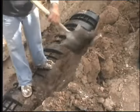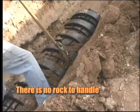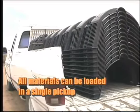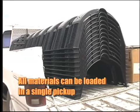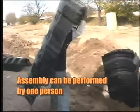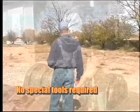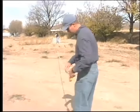The chamber systems have a number of distinct advantages. There is no rock to handle. The materials for an entire drain field can be loaded on a single pickup truck. The assembly can be performed by one person, and there are no special tools required. But there are a number of cautions.